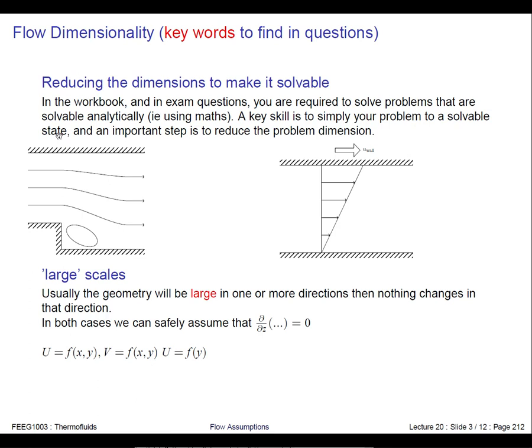So in this particular example in 2D, we can say, well, the horizontal velocity component u is a function of the x and the y positions, and the v component of the velocity is non-zero, and it also depends on the x and y positions, but neither of these depend on the z position, and the w velocity, if you like, the velocity out of the page, is 0.